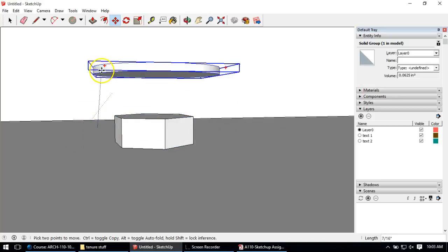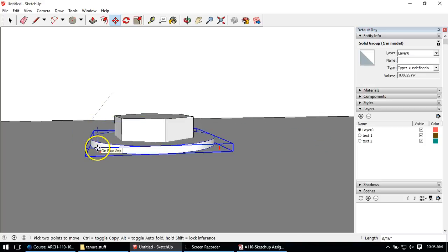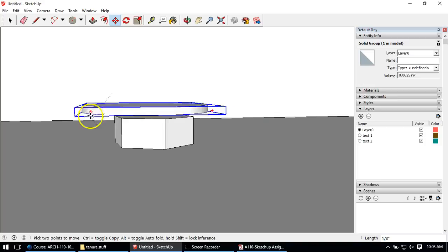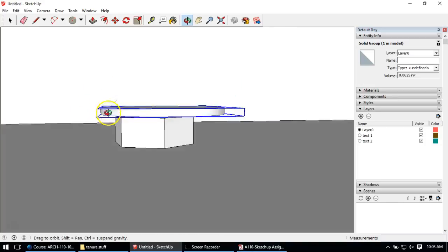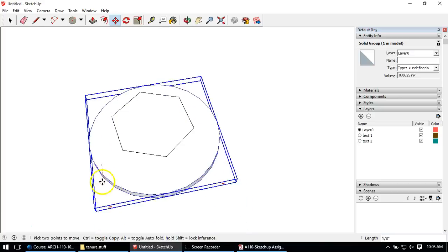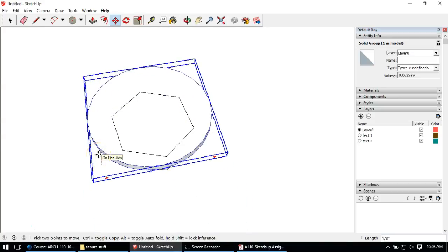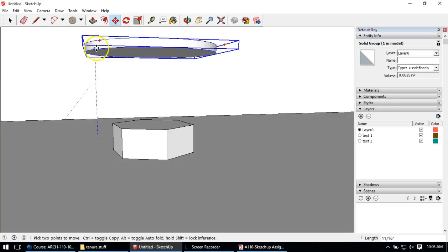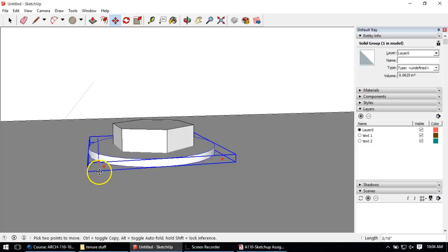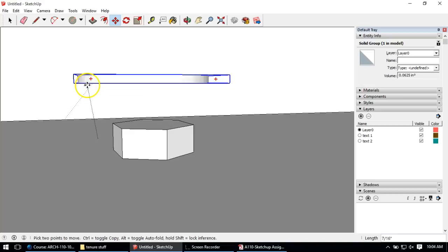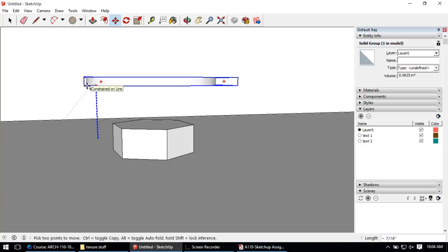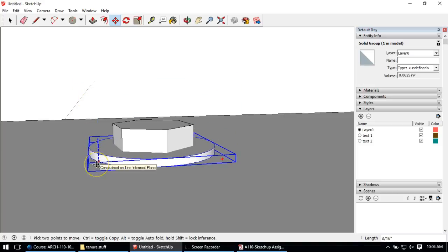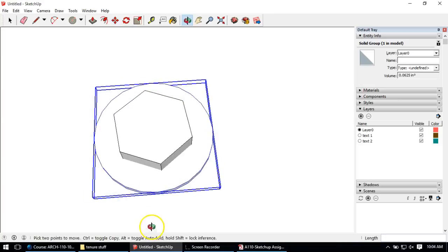Now, you want to make sure that you move it down, so I need to see the blue axis. And now I can see I've got it right here, but if you're having problems finding the blue axis, there are ways that you can get to it. Either change your view, because if I'm like this, I can't move it down. SketchUp just doesn't have the view to be able to see what is up and down in this view. So it'd be very difficult. Another way of doing it is to move it up, if moving it up is easier, and I get the blue line and I can hold shift and lock it into the blue. Alternatively, I can get to blue by pushing the up arrow key or the down arrow key on my keyboard, and it will lock into that blue dimension, and I'll make sure I got it perfectly straight down.